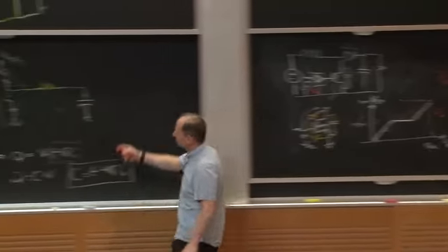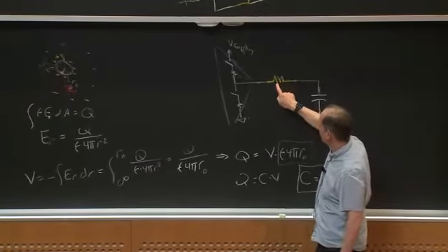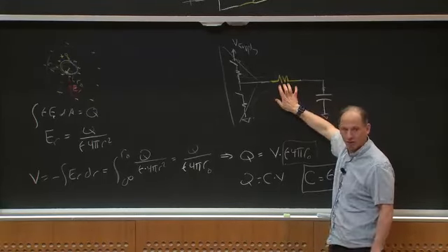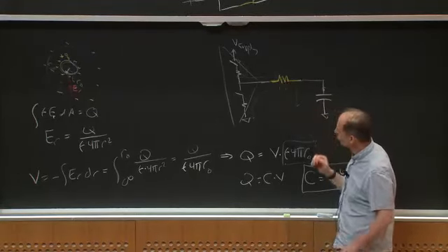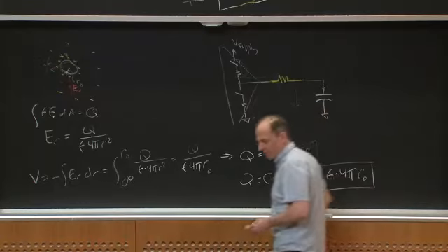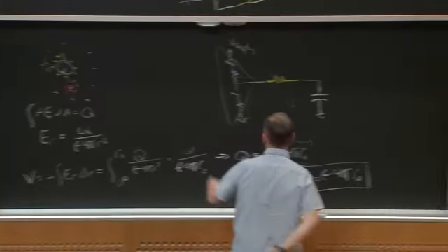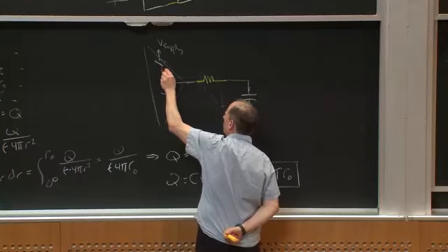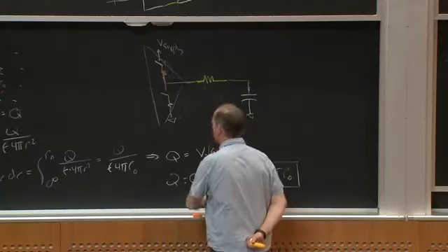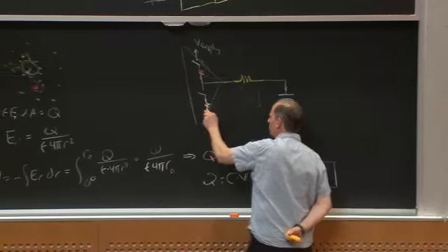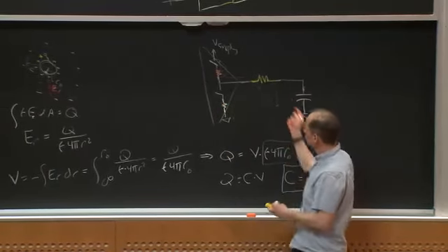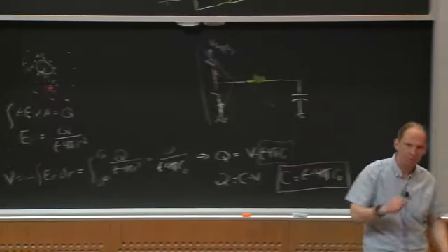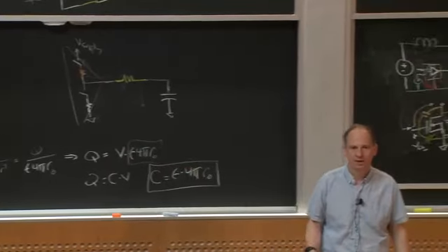So if I load it all into this resistor, I don't want this resistor to be the same for turn on and turn off. What you'll see in a lot of drivers is that for turn on, this resistance, or equivalently the positive sourcing capability, will be a bigger resistance, and the resistance for turning off will be a much smaller resistance. So you can turn the transistor off fast, but turn them on only slightly slow, and that'll help reduce your noise. Okay?